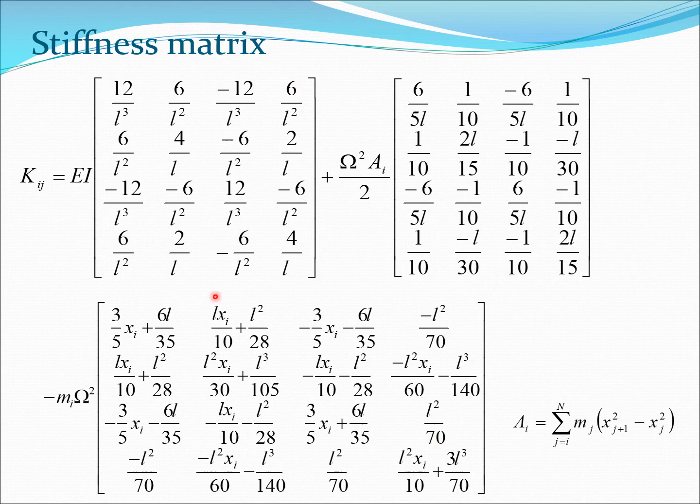And the first term is going to come out very easily. That is the term involving just EI, because EI comes out of the integral, EI being a uniform value as we have assumed here, and then you have this is a function of L. But you get two terms here which are functions of the rotation speed, and these terms are somewhat complicated.